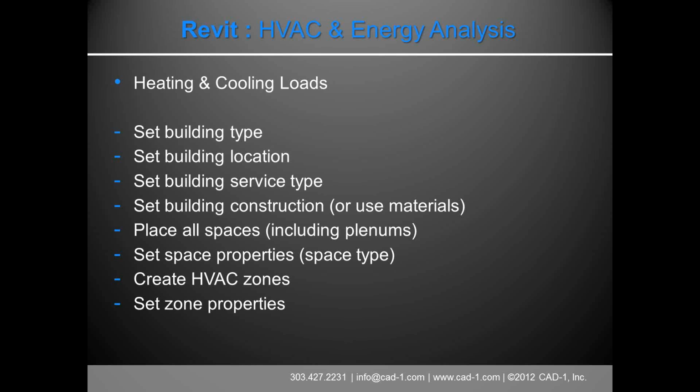So you want to place all spaces, including the plenums. If we have time at the end, I might demonstrate that. So above, say, a drop ceiling, the architect has rooms in there, and you place spaces in there. You want to go into those and make sure there's a space element, because that's what's being used for the energy analysis, for the load calcs. And then you want to set the space properties.